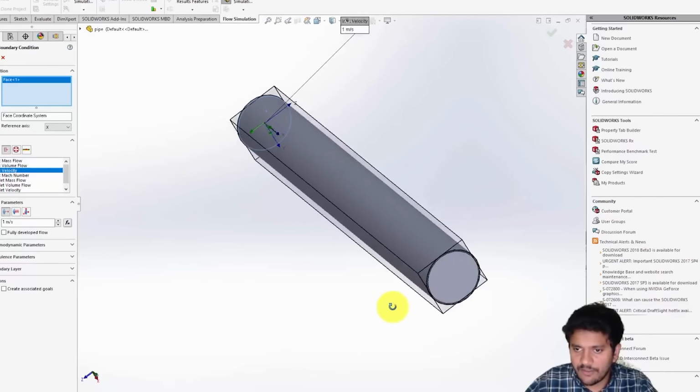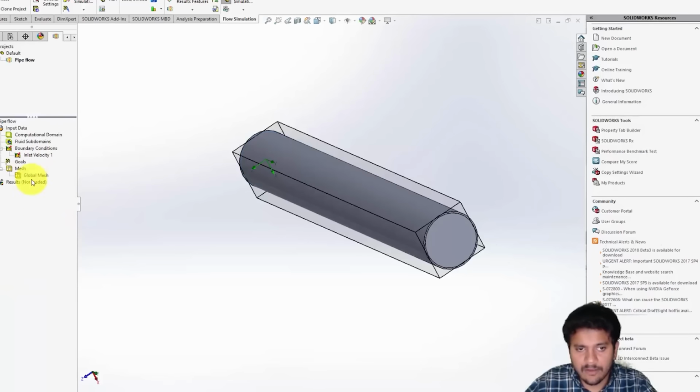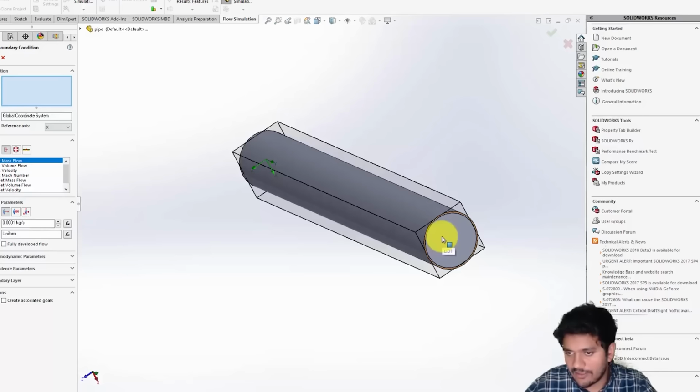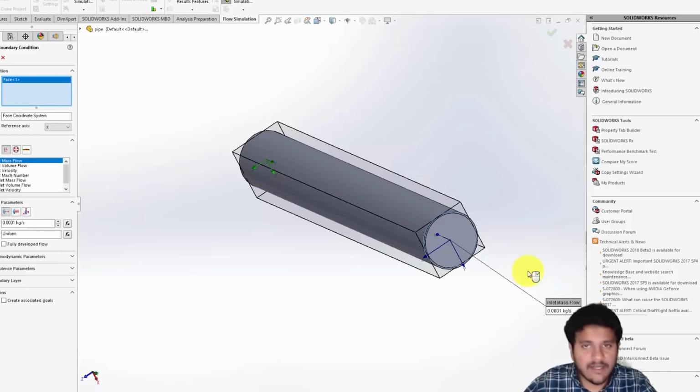And in the next phase, let's just click OK here and do the same thing again. This time I'm going to right click on the other phase, click on select other, and make sure that you select phase at lid 1, and in the bracket you see pipe. Okay, so that's the name of your simulation, right? That's the name we gave initially. So you need to see that name, okay? Whatever the name that you gave, make sure that you see that. Do not select this option, that's the wrong one. In a later video, I'll comment on why that's the wrong option.